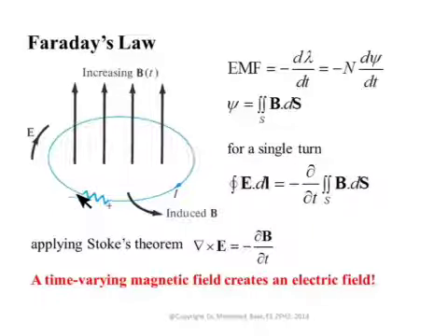What is this current trying to do? This current is actually trying to create flux opposing the change in the original flux. If you have a current flowing this way, then it creates a flux in the shown direction. So you can see this created flux is trying to stop the increase in the original flux.